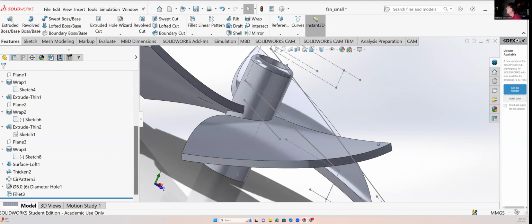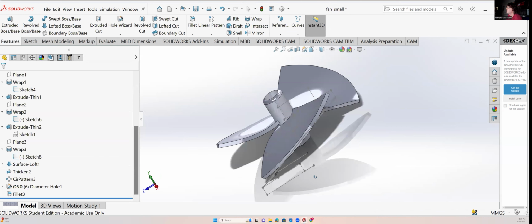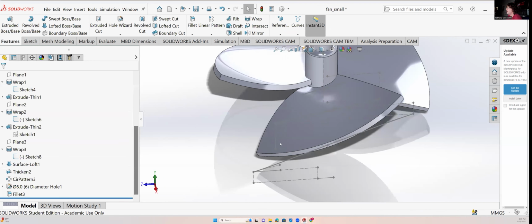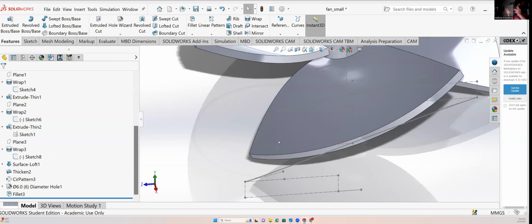Yeah, I wouldn't normally make a fan that's shaped like that. I don't think it would be very efficient. But yeah, normally you want to have a more severe angle at the roots with a lot of impellers or propellers. Usually you want your pitch at the root to be higher, and the root being closer to the hub, the center of the rotation.